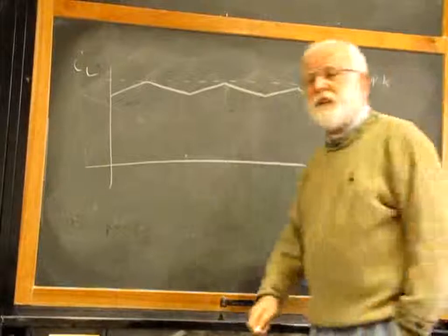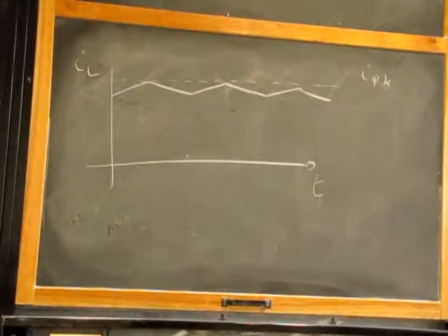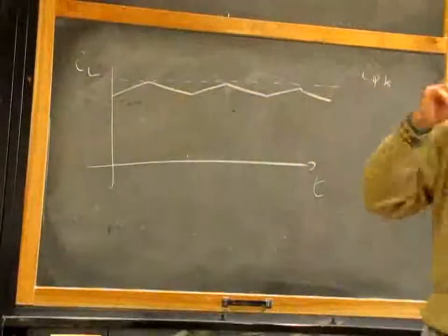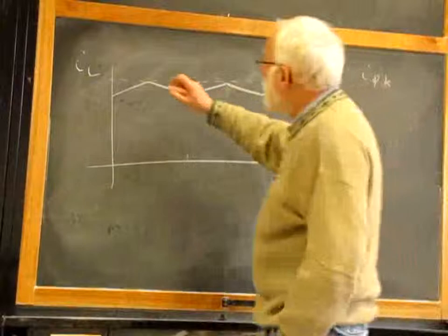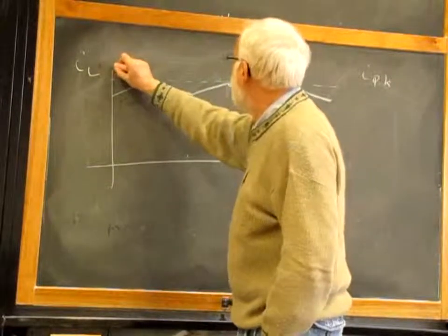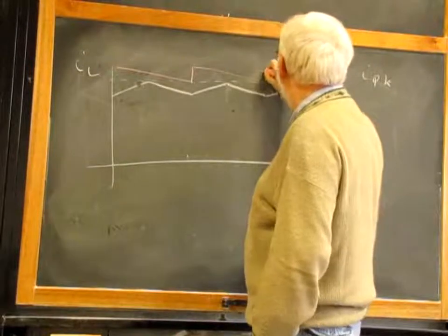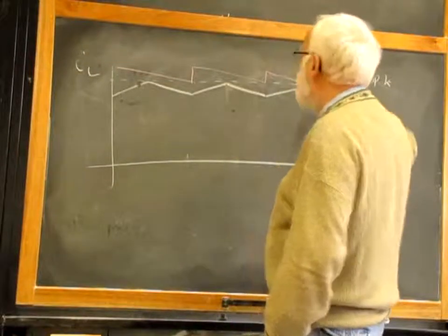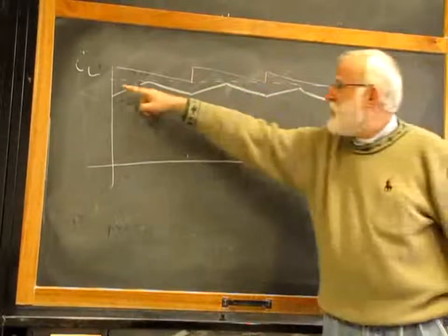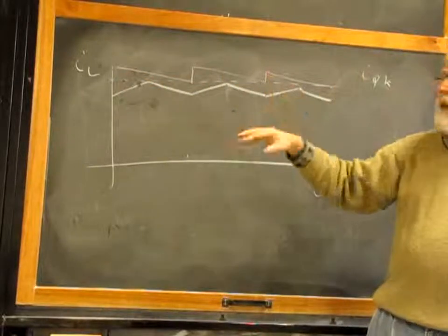So, we learned that in order to bring this error to zero, you need to add to the peak value that we want a sort of compensation ramp, something like this. And obviously this red curve must be shifted down a little bit in order to get the peak value to be just the average value we want.